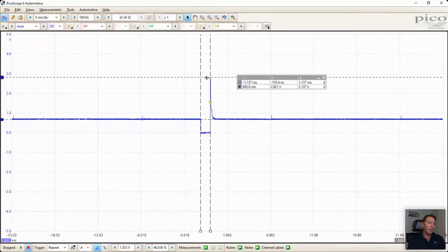And our second line back here, again, it depends on the injectors used, but you're going to see upwards of 60 volts, maybe on average 80 volts. If you do this on a diesel injector, you're probably going to see around 110, 120 volts back EMF bridged up there. And again, I like to use those because I like to look and see how much back EMF is generated. Too much and we've got issues in our system. Not enough, we've probably got shorts in the injectors or the injector coil windings. So again, it might be something we want to use to compare injector waveforms. In this case, it's an injector waveform. I might want to use it to do some pressure comparisons.